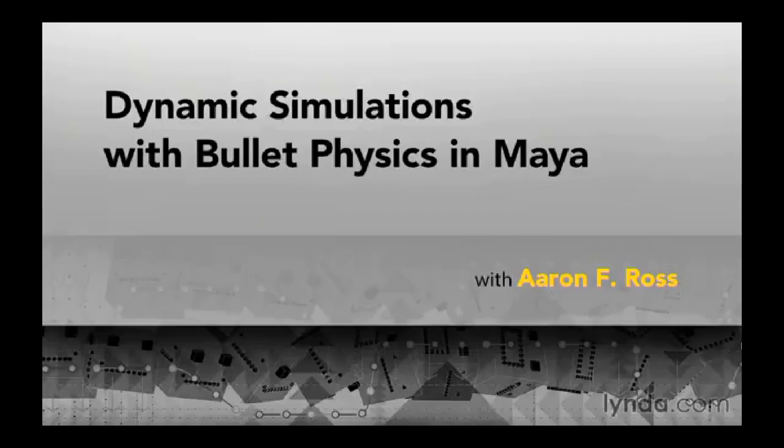This short course covered the major features of Maya Bullet, but there's always more to learn and experience. What you'll find with Bullet is that its value as a production tool only increases as you pile on more complexity. It's a massive improvement over the old school classic rigid body and soft body solvers in Maya. If you've got a solid video card with at least 1 GB of memory, then try enabling OpenCL acceleration in the Bullet solver node. You may find that it allows you to simulate ever more complex scenes with hundreds or even thousands of rigid bodies. That's something we could never do before in Maya, so it's really exciting.